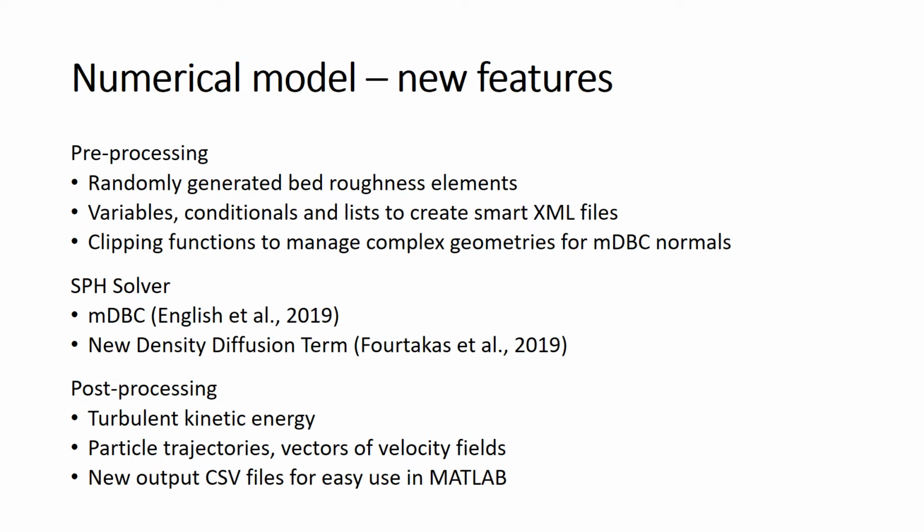However, the use of modified dynamic boundary conditions for the simulation of the complex geometries required for this work promoted significant advances in pre-processing and post-processing, such as randomly generated bed roughness elements, clipping functions to manage complex geometries, turbulent kinetic energy calculation, particle trajectories calculation, and new output files for easy use in MATLAB. Most of them are already included in the latest update of the DualSPHysics package. The main features are briefly described in the following slides.